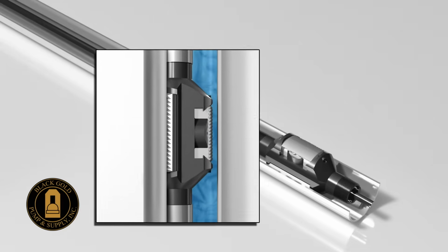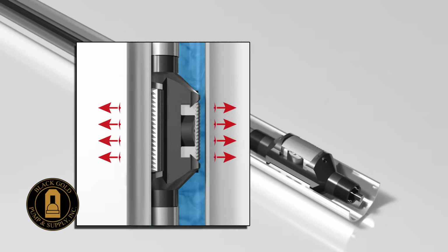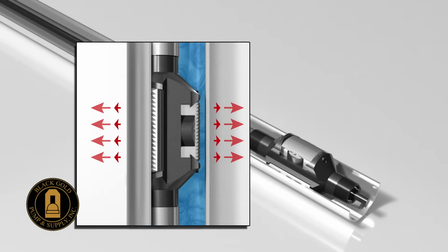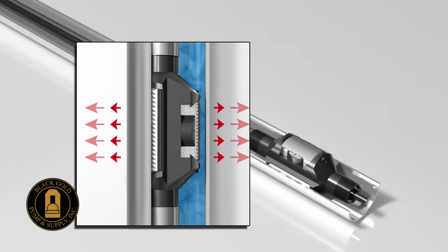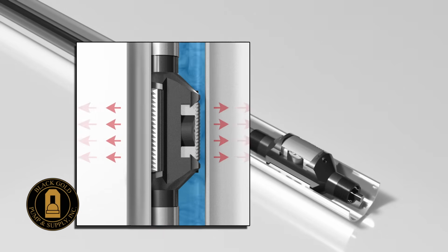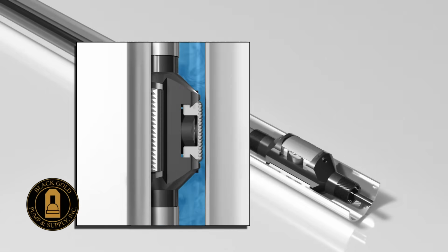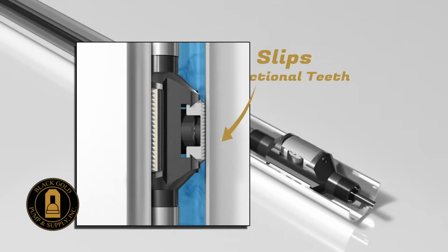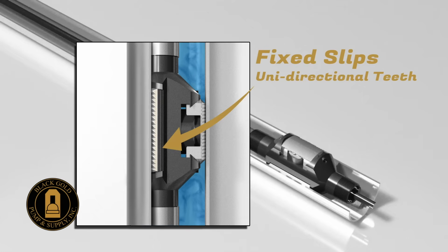The hydraulic tubing anchor works much like the braking system in your car or truck. The increased load from the fluid filling up the tubing causes a differential pressure between the tubing and casing. This additional tubing pressure is exerted on an internally exposed piston that is attached to an external live slip. As the anchor piston protrudes outward, the live slip presses up against the casing internal diameter. The fixed slips on the opposite side of the anchor have unidirectional teeth that are tapered downward. This taper allows the anchor to slide downward but resist upward movement.